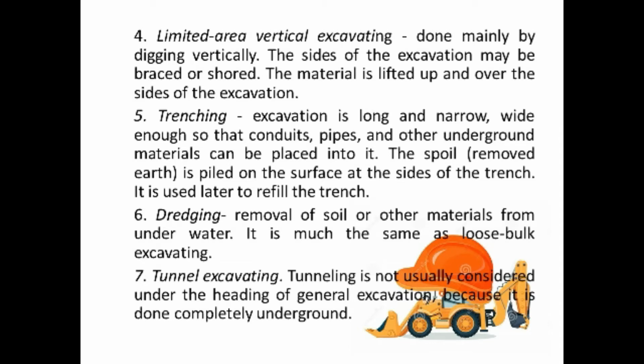Next, we have dredging. This is the removal of soil or other materials from underwater. It is much the same as loose bulk excavating. An example of dredging is the practice we use for making harbors or rebuilding channels which are deeper. Tunnel excavating, or tunneling, is not usually considered under the heading of general excavation because it is done completely underground.